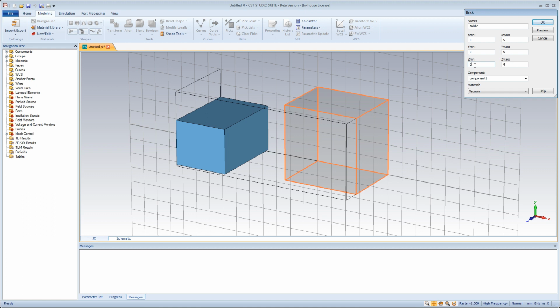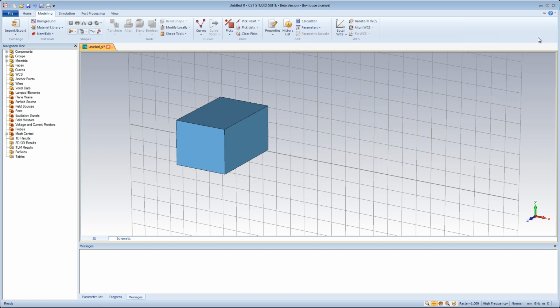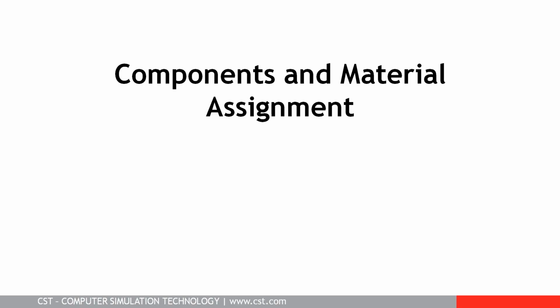In this case, the shape dialog box will open immediately. Pressing the escape key twice aborts the whole shape generation process. Hitting the backspace key deletes the previously selected point. If no point has been selected, the shape generation will also be aborted.